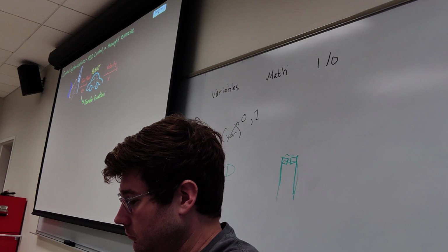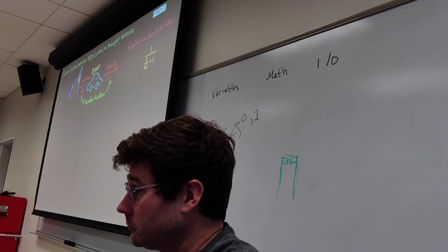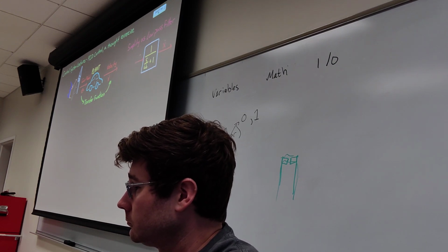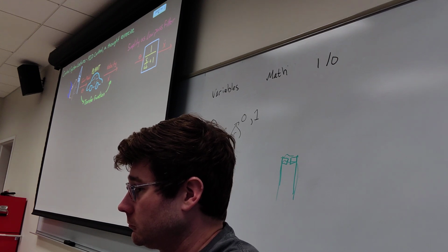We need a transfer function from the gas pedal position to the velocity of the car. Now in real life, this is a complicated nonlinear transfer function that's dependent on the car model. However, you can simplify this model by assuming it's just a first-order low-pass filter. And the transfer function for a low-pass filter looks like this, where the output is velocity and the input is angle. So let me explain why this is a reasonable estimate.